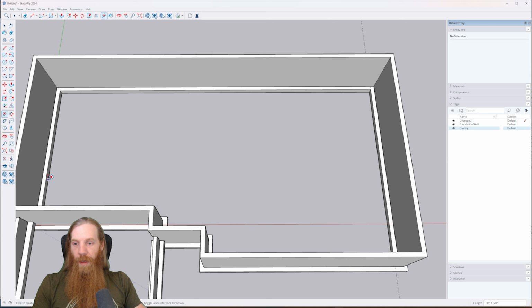Those will carry load from the joist downward so that the span of the joist is shortened to, let's say, only half of this distance, right? So you have like a 15 or a 12-foot span for your joist. Now you can go with something much smaller, like a 12-inch I-joist. That will work just fine in most cases, so you can save yourself a lot of money on the design of your floor system, right?